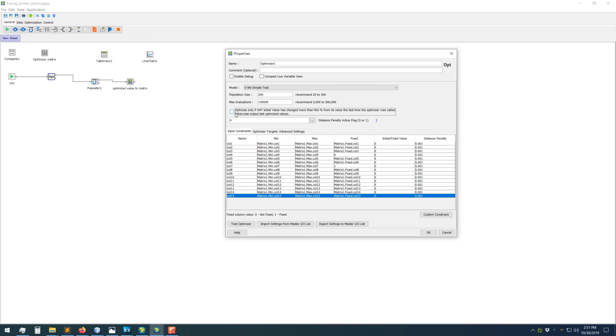This option is a little bit outdated now that we've added some new features into the optimizer. The distance penalty for one, and also the fact that every time the optimizer starts, it utilizes the current initial conditions as one of the particle positions. So one of the particles is seeded with the current operating conditions. So if the current operating conditions are optimal, especially when you use that feature in combination with the distance penalty, it pretty much ensures that the inputs aren't going to move around unnecessarily.